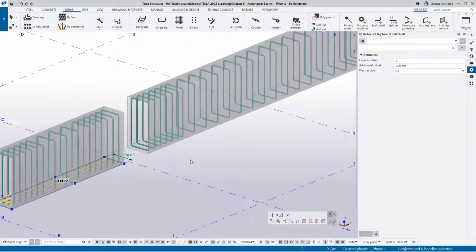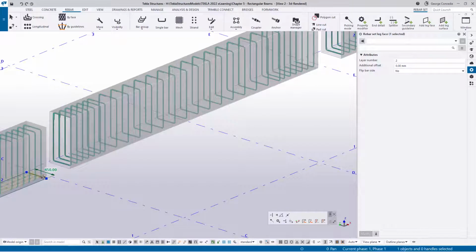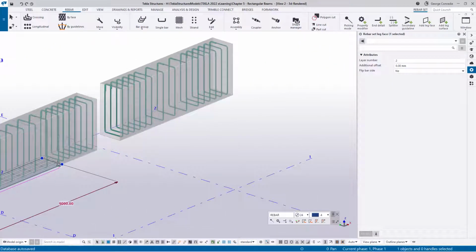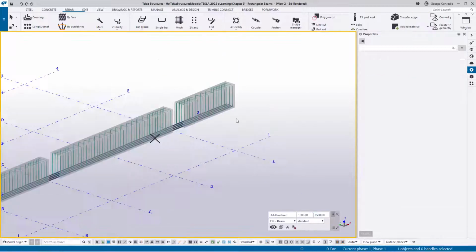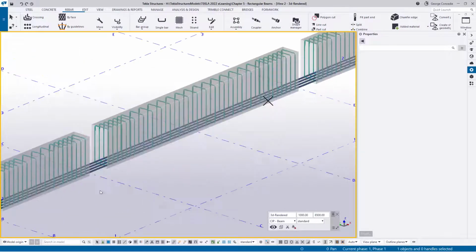And then we can basically just grab that edge, and you can see how Tekla holds it in that plane because we're forcing it in that plane. So it doesn't really matter where you snap to now. You can really just pick a point or whatever, and it will keep it in that plane. It's not in a 3D plane. So that pretty much extends the bar across the whole lot. Now, this gives us the option to use a splitter and then do our detail at the bottom.